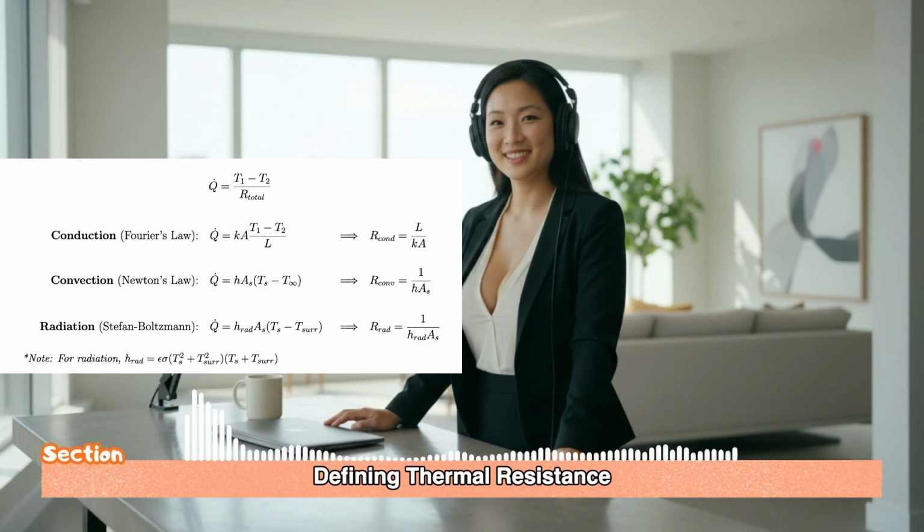And this formula tells us something really powerful about very efficient heat transfer processes, like phase change. If h is extremely large, approaching infinity, like during vigorous boiling or condensation, then the resistance, R conv, would approach 0. It would. And in that scenario, with zero resistance, the surface temperature, Ts, must become basically identical to the fluid temperature around it, T infinity. It means that boundary offers almost no barrier to heat transfer at all. Which is why engineers work so hard to increase h in things like power plant condensers.